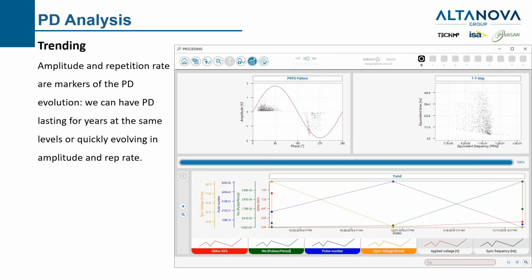Normally, the idea is to use the PD diagnosis for monitoring. Let's say every 3 months, every 6 months, we have data and we compare the data with the old ones. We try to recognize the same phenomena. In case we see an evolution, we trigger the asset management's attention to spotlight a particular phenomenon. This can be brought into a maintenance action or into a visual inspection to find out what the issue is and if there is a necessity of any maintenance intervention or even rewinding.